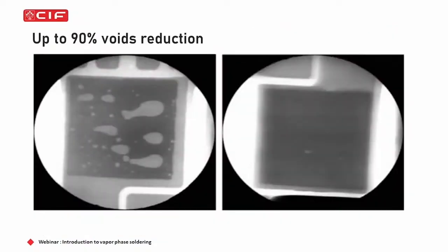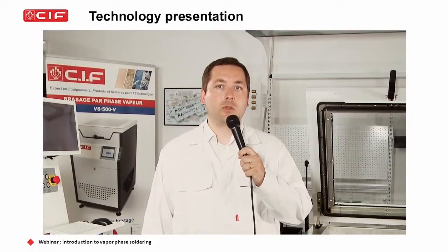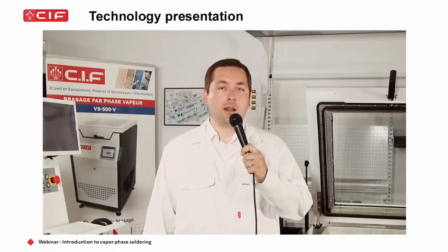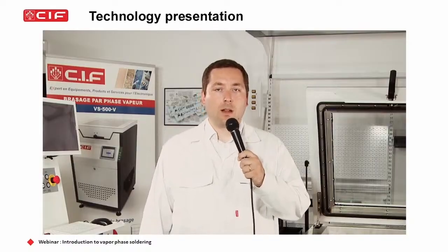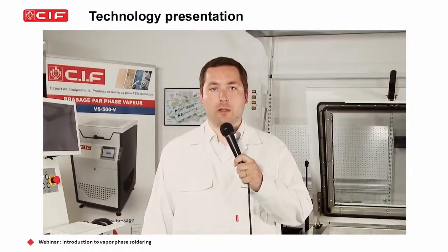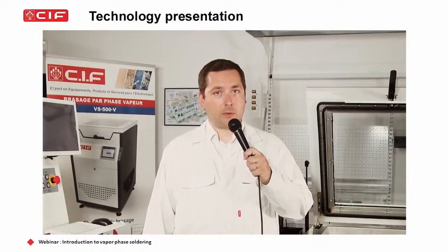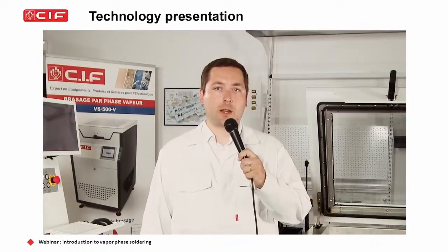So the fourth benefit of the vapor phase technology is the void reduction. It can reduce by up to 90% the amount of voids created during the soldering process. This is a reduction compared to conventional reflow soldering. This means for most applications, voids will be a non-subject.